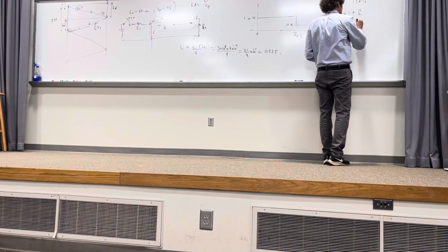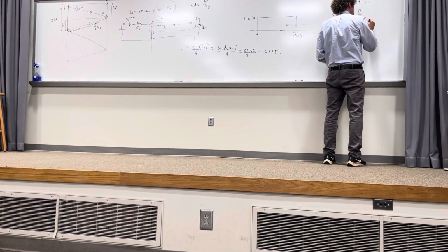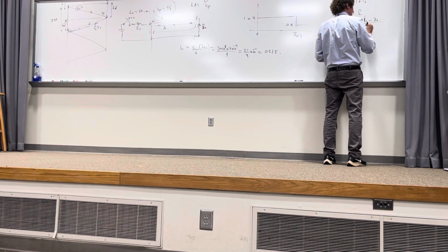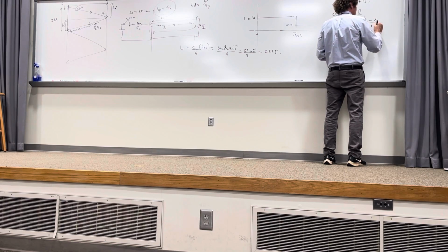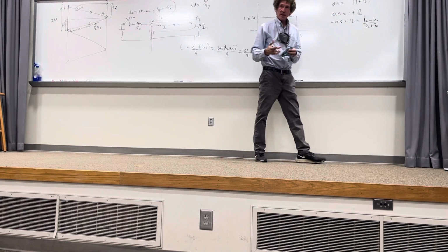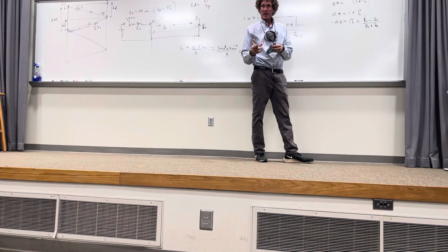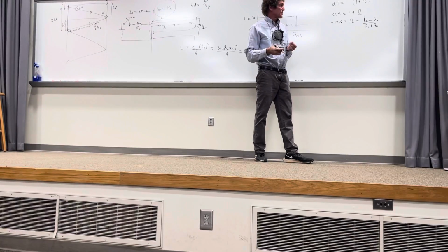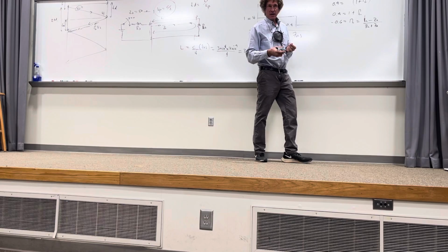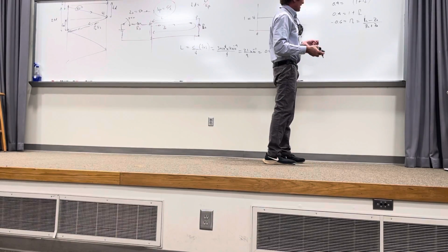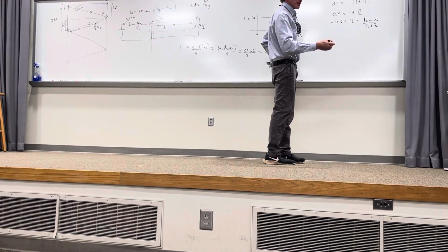Well, it's equal to the load impedance. In this case, it's a strict resistance, so I just call it R load, right? Minus the characteristic impedance of the line, Z0, the impedance I came from, over R load plus Z0. Y'all agree with that? Now, Z0 is 50 ohms, correct? I could actually normalize, but I'll just brute force this thing.